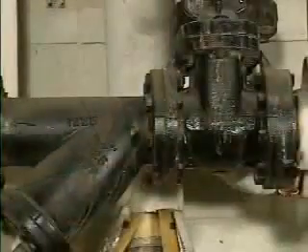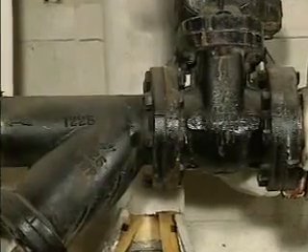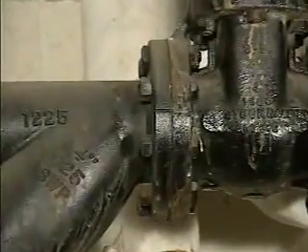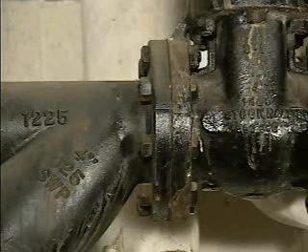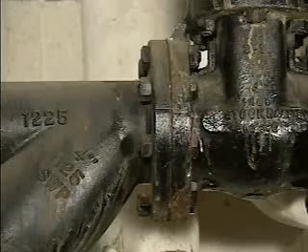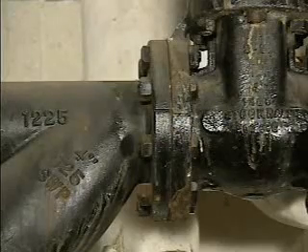For this reason, it is often used in high pressure and high temperature systems, such as hydraulic systems that push and lift heavy loads. Another characteristic of carbon steel is that it's less brittle than other materials, such as stainless steel, so it's able to absorb vibrations. Therefore, it is well suited for systems that generate significant vibrations, such as in vibrators used to make anodes in aluminum manufacturing processes, lifts, and large gearboxes attached to motors or turbines. Because it is susceptible to corrosion, carbon steel is generally used with non-corrosive gases and liquids.